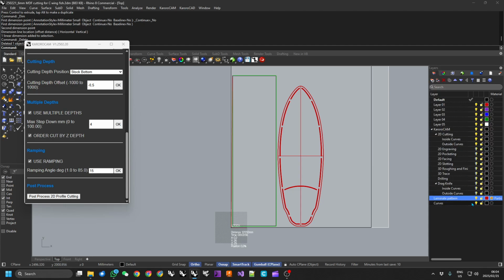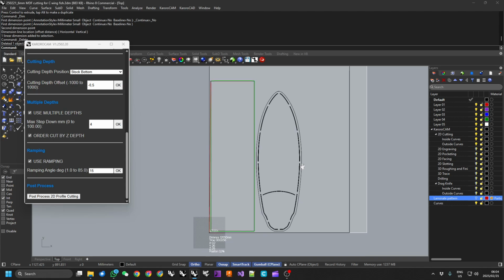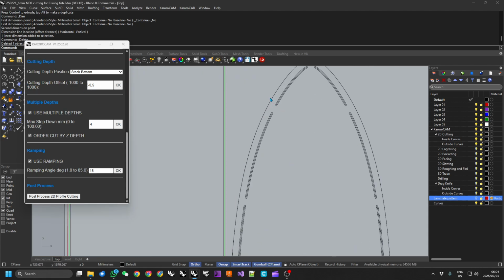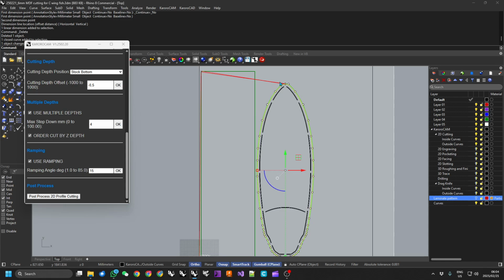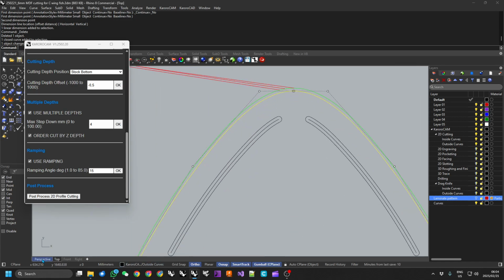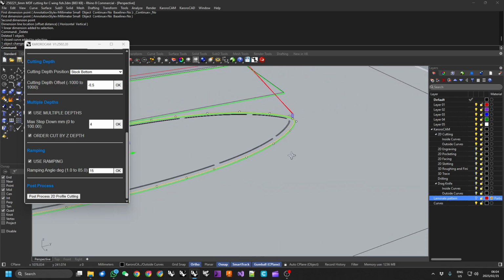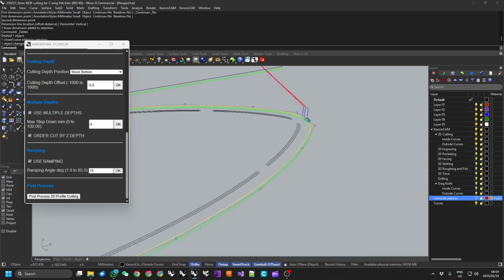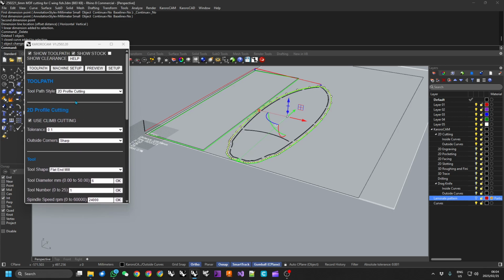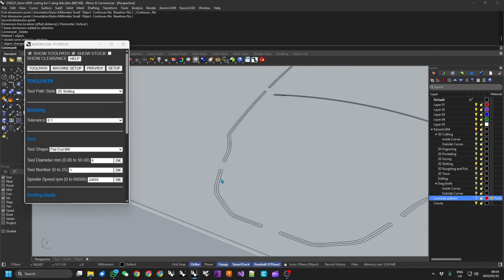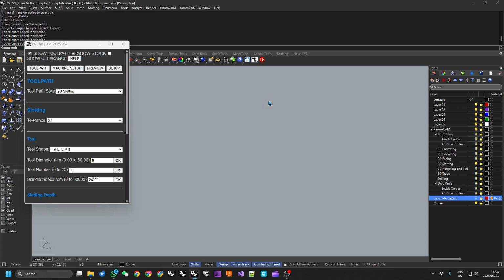I don't need now to be seeing that laminate pattern, but I can take this outline, and if we shift that to outside curves, we can pick that up as also to be machined when we come to machine this other outline. And then I'm just going to change from 2D profile cutting to 2D slotting. We're going to come in and pick up all of these internal curves.